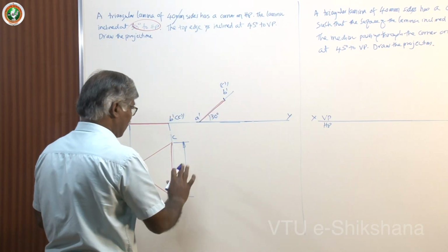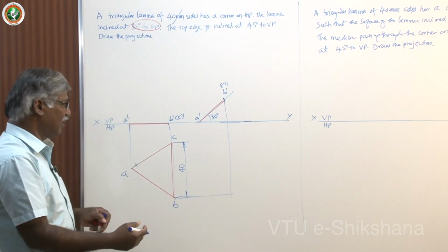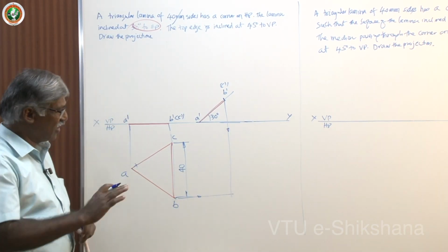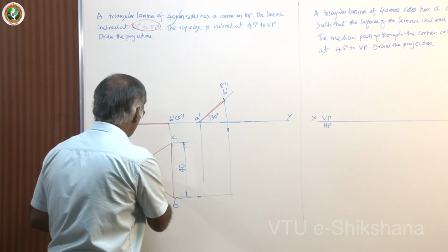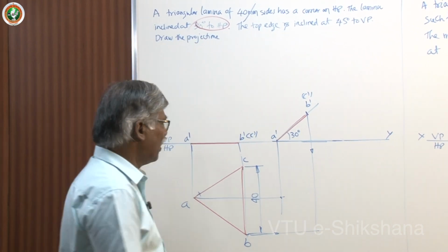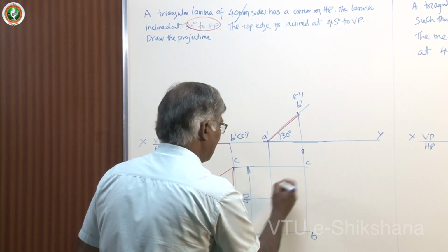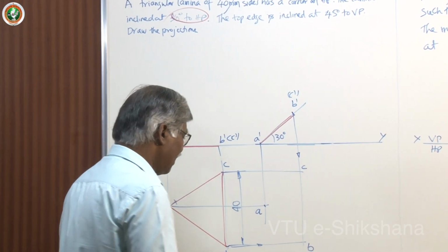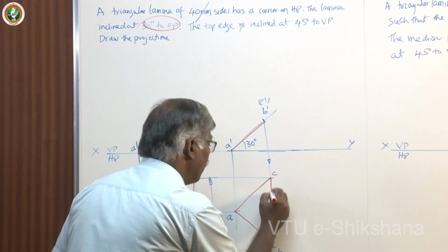How to project? You should not unnecessarily draw a number of lines. See, I always say, insist on this. Right extreme projection, the bottommost projection. Keep it so that unnecessary lines can be avoided. Now, A is this. Draw it. As usual in computer, the alignment indicator is there. Easily you can do it. Now, here is C. Automatically you get B here. This is C. This one is A. Join these three to get the top view in the second figure.